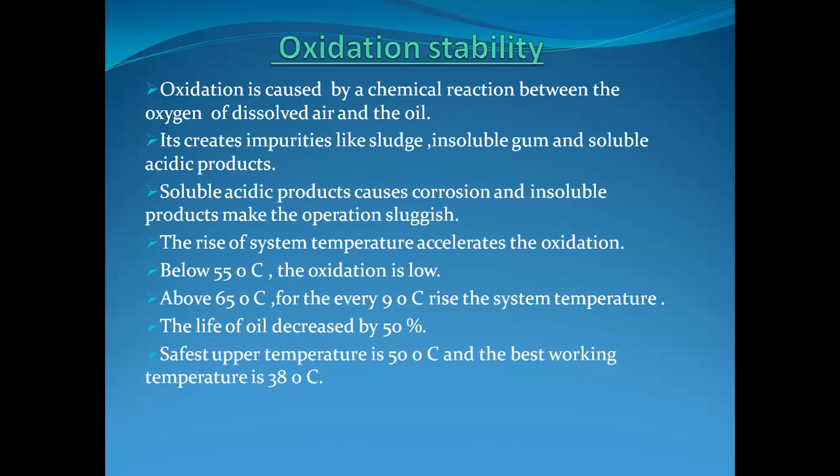Therefore, the safest temperature is 50 degrees Celsius, and the best working temperature is 38 degrees Celsius for the hydraulic fluid. So, maintain the temperature of the hydraulic fluid at around 38 degrees Celsius. If the temperature goes above 65 degrees Celsius, an oil cooler must be installed to reduce the temperature to 38 to 40 degrees Celsius. Demulsibility.